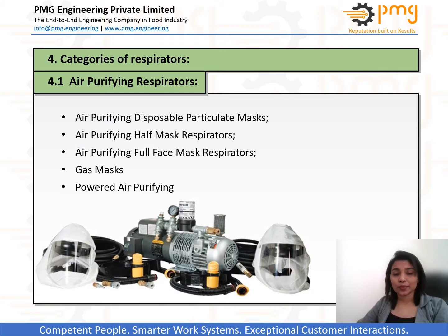We looked into possible hazards and types of hazard that can affect our respiratory system. Now coming to the important part, how to prevent or avoid hazardous situations at the construction site. Using respirators is one major prevention method. Respirators are coverings consisting of air filtration units and are fitted very close to nose and mouth. The two types of respirators are air purifying and airline respirators.